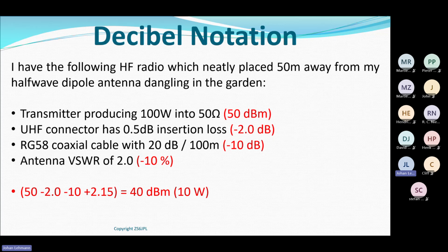But here's a good thing. I'm using a half-wave dipole antenna, and that's got a gain of 2.15 dB above my reference, being an isotropic antenna. So at least there I'm gaining 2 dB.